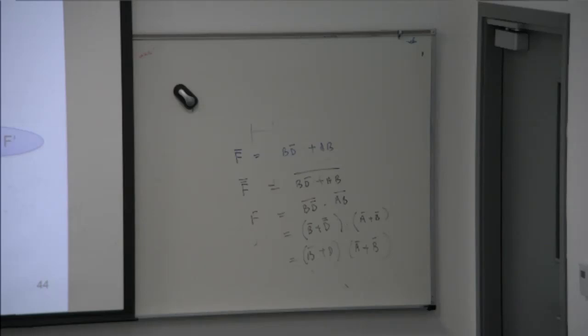Maybe it's also possible that I give you the sigma form, and ask you to derive the SOP expression for this sigma form. Then you convert it into the pi function. When you convert it into the pi function, you put 0 in all of this pi function, and then you can solve it directly. So there can be a lot of methods. Got it? And we also know how to convert from the sum of products form to the product of sums form.